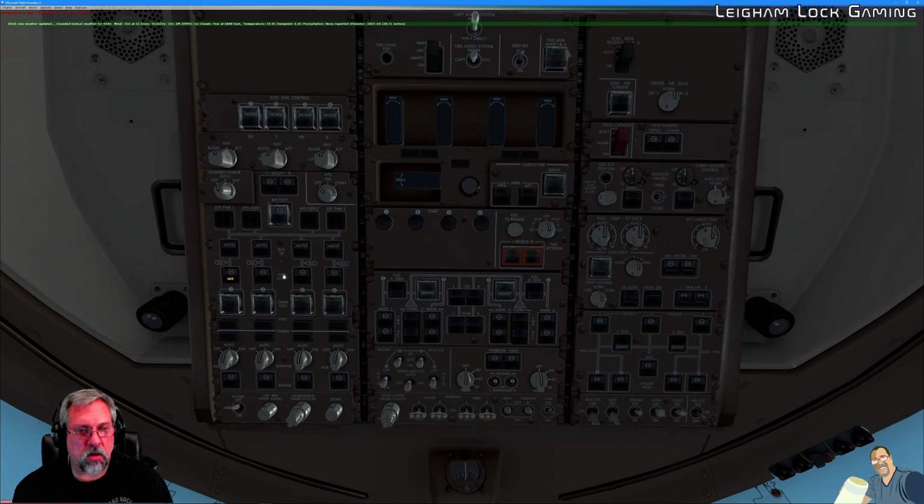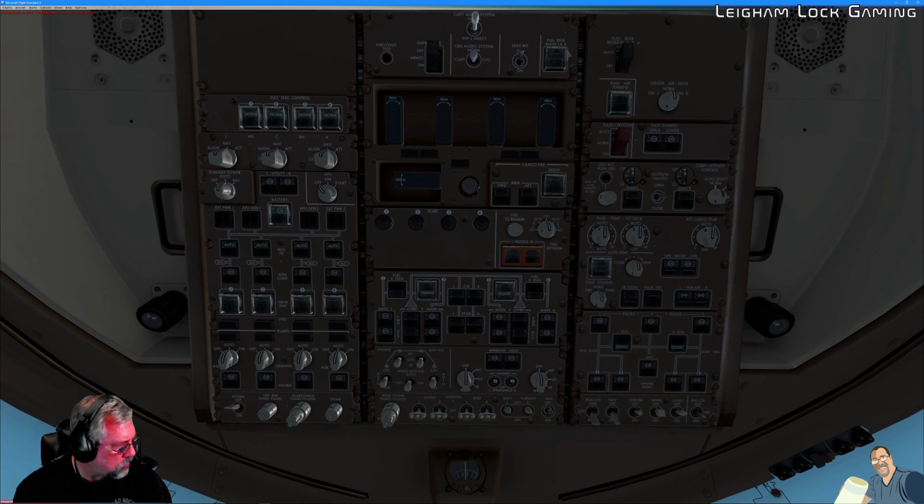And we got one little hiccup here with generator control 1. We're going to click that off, click that back on to clear that indicator. Looks good. No change required to engine anti-ice. Pack switch is already turned back on. Ground crew says the ground equipment is clear. We want to prepare for takeoff, so we want to go to flaps 10.